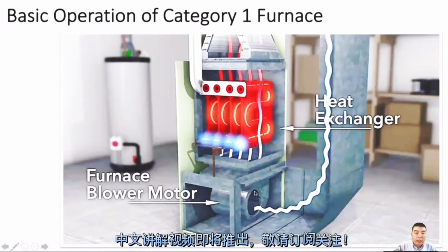It's harder to check the secondary heat exchanger, but you can check the A coil, because normally the secondary heat exchanger is dirtier than the A coil. So if you see the A coil is dirty, that means the heat exchanger is dirty. You should make notes there, and they need the gas technician to go there and check and clean the secondary heat exchanger.